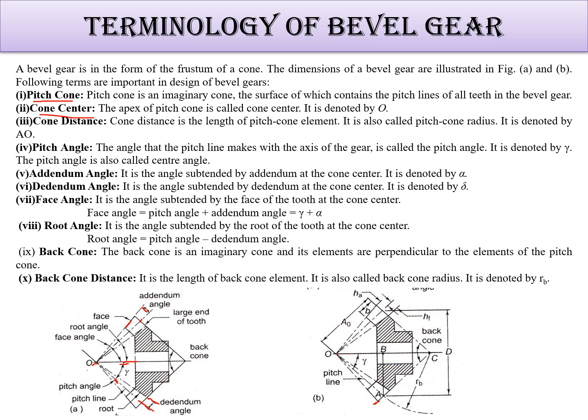Now in cone, one more thing is the back cone angle. So this is the back cone angle because the front part is the spherical part. We can't use it for designing the gear. That's why the whole procedure is done with the help of the back cone. We are going to see it in the next slide also. This is the imaginary cone and that is the back cone, which has a flat surface. So back cone distance is what? From this big C point, this is the radius RB, and this continues like this and creates a flat surface.